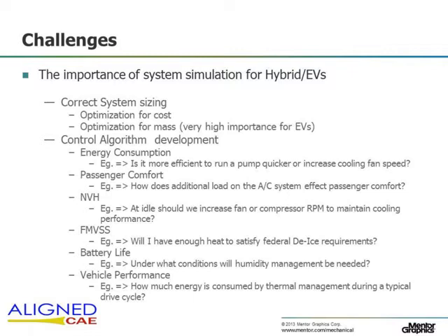Now that the internal combustion engine is eliminated from the vehicle, we no longer have a considerable amount of waste heat available. For an EV, it's even more of a challenge because there is no engine at all, so we need to add active heating in the form of things like PTC heaters. Battery life.